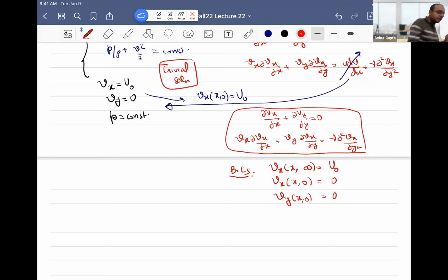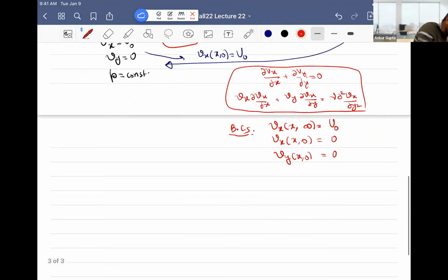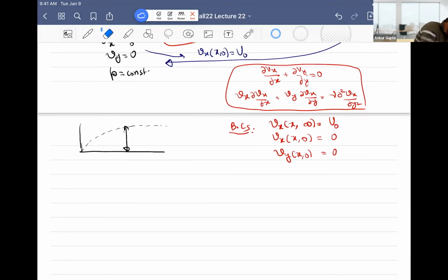I want to make sure this is very clear: now we will be doing order of magnitude analysis on a general x. And to not confuse you, I will write this as delta x of x, some sort of a delta x of x. This is just to mention this is a position dependent boundary layer thickness.